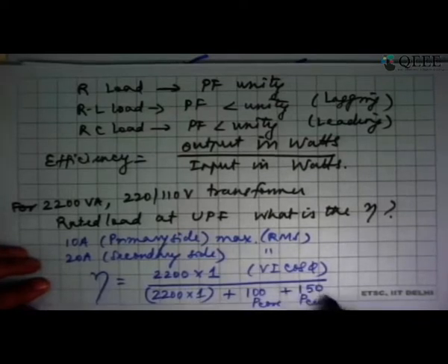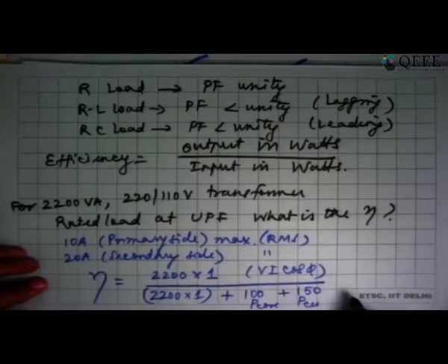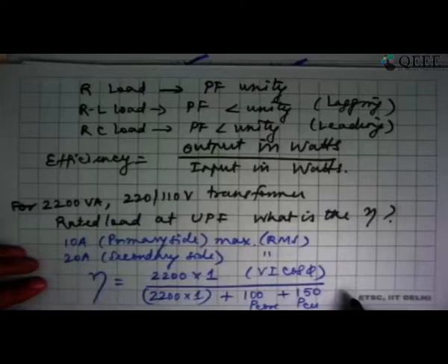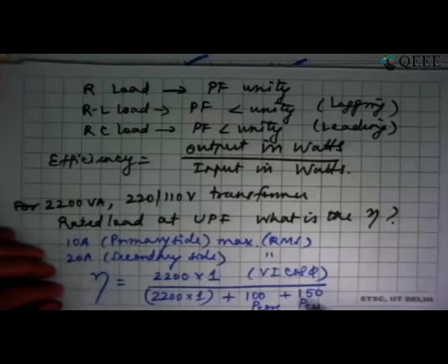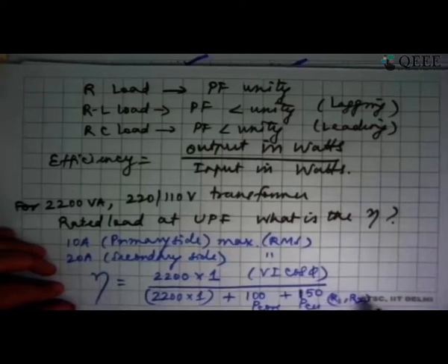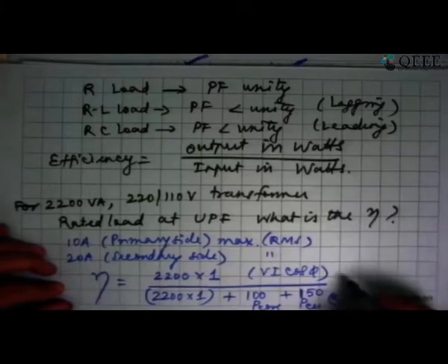Clearly the copper loss is not influenced by the reactance. There is one question from one of them: is there any effect from the reactance on efficiency? The efficiency will not be influenced by the reactance because the copper loss is influenced only by R1 and R2, and the core loss is influenced only by hysteresis and eddy current. So directly your X1 and X2 will not be affecting the efficiency.